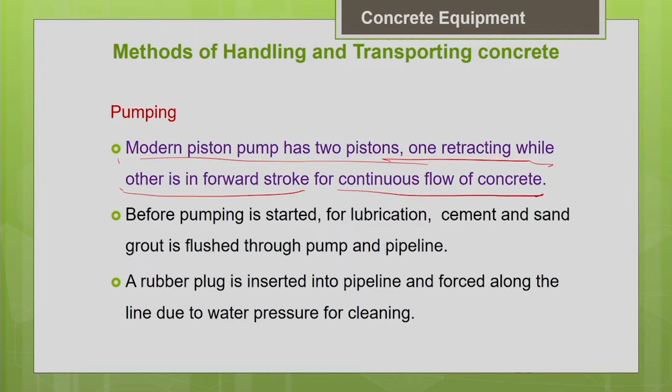Another important thing to be noted with respect to pumping: pumping is a relatively tedious operation, because before you pump your actual concrete mix, you have to do some lubricating or buttering kind of job, as I told you earlier for the conventional drum mixers.